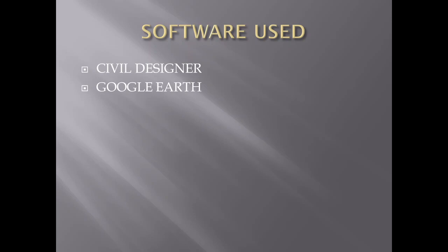First, set up the project. You will have to open a new folder on the desktop and name it. You will then open Civil Designer, then click a function known as Survey Mode. Go to File, Project Settings. Click on Terrain, and then save the file. That is where all the information that you will do further, such as the roads, the curbs, and the drawings, will be saved too.